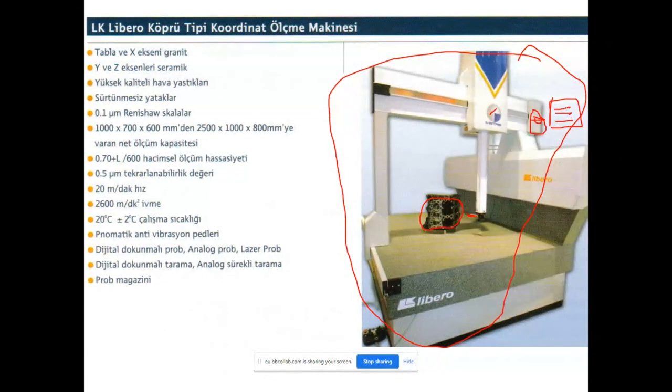Using the software, we can see the measured value. Output is electronic, input is mechanical. The irregularities over the surface of the object can be sensed by the probe. The extension may push the probe. It is a mechanical effect, and that mechanical effect is converted to a digital signal. And the digital signal is displayed on the display of the instrument.